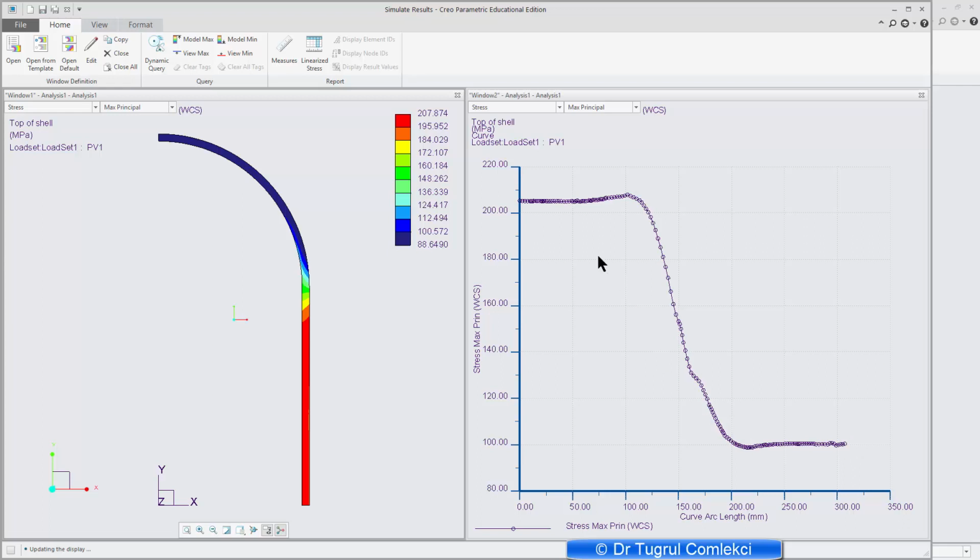What you'll need to verify these numbers with is PR upon T for the cylindrical portion and PR upon 2T for the spherical portion, as we discussed in the lectures.